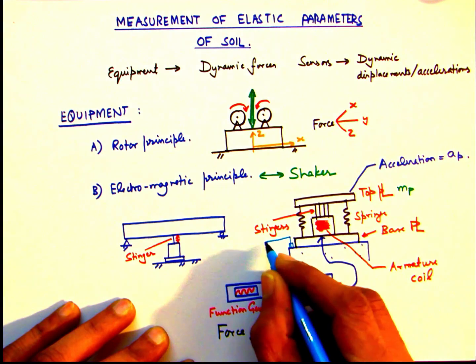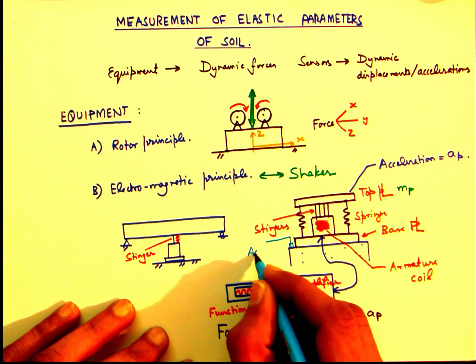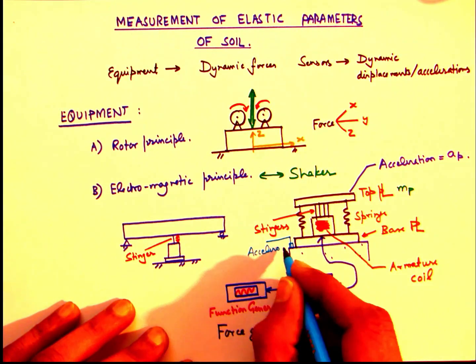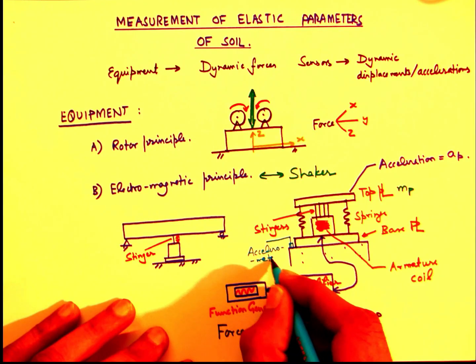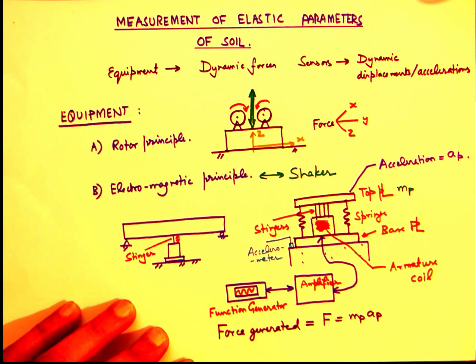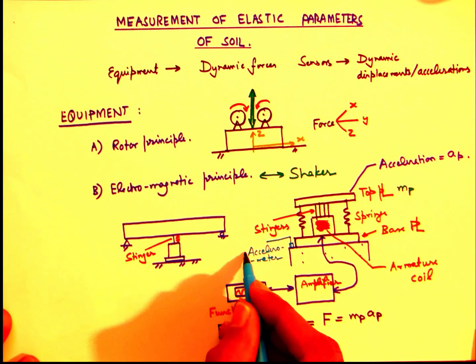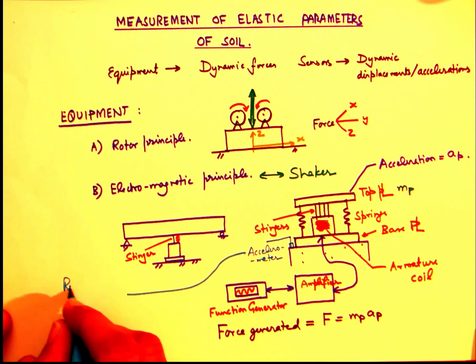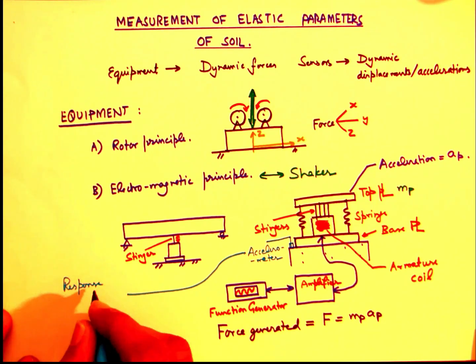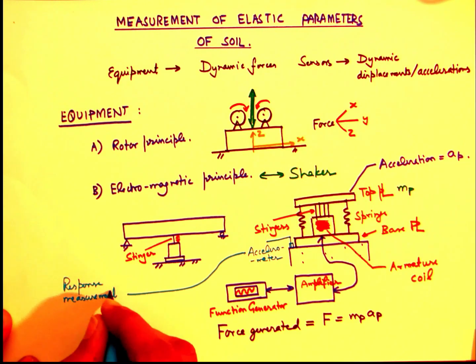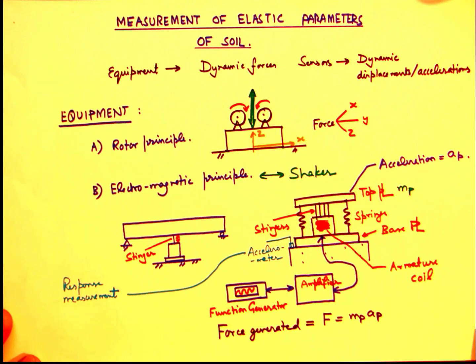Now the next measurement related to vibrations is the measurement of acceleration at the base of the shaker. So this could be the floor or it could be the machine foundation. For this purpose, we may install an accelerometer at the base as shown here. So this basically measures the response and the vibrations induced on the host structure or the floor.